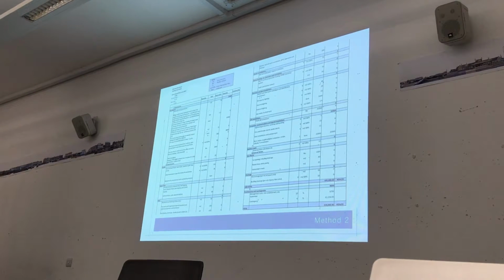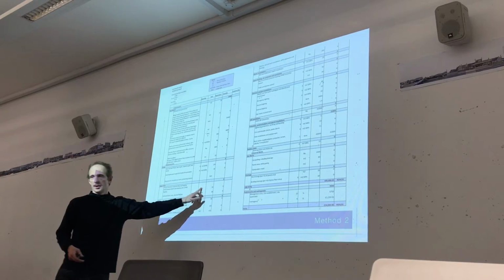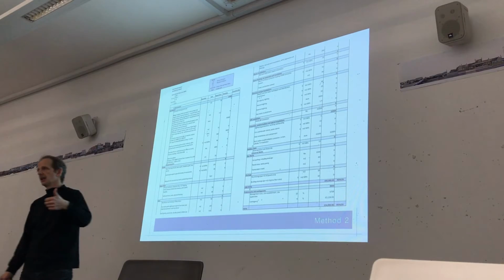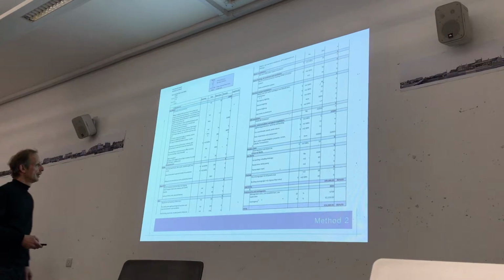So if it's just got, there isn't one on there, but if it's just got metres, it's just looking for a length. So if it's handrails, for example, for a staircase, you measure that in linear length. So you've got 10 linear metres of balustrading. And some things are items, so where you've got one of them, like a lift, we don't break that down into all its component parts. We just put it in as a lift, one lift, and that's an item, or one reception desk, and then we might put a lump sum figure in for that.